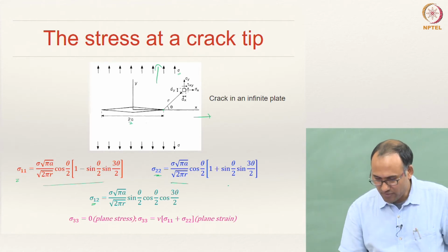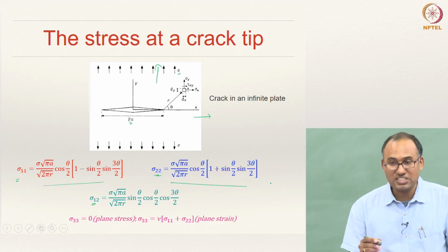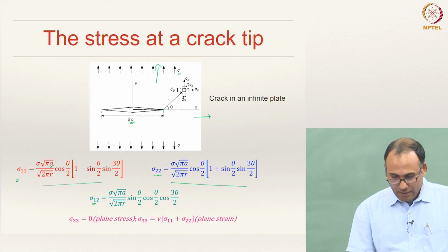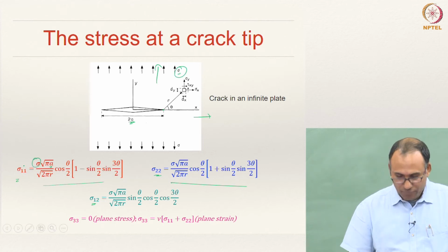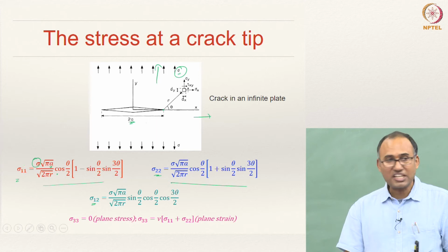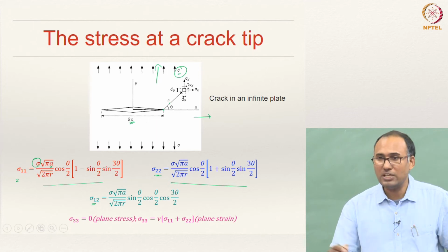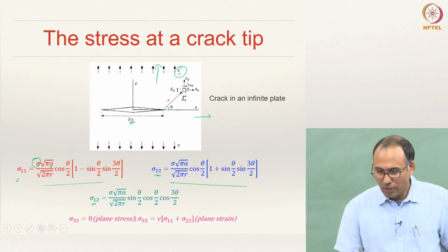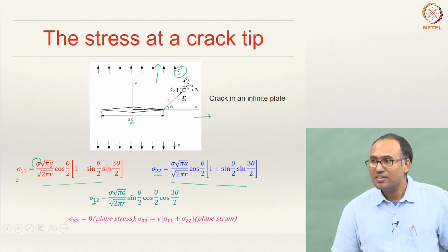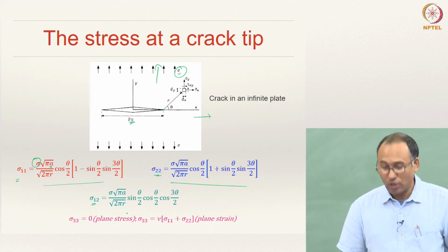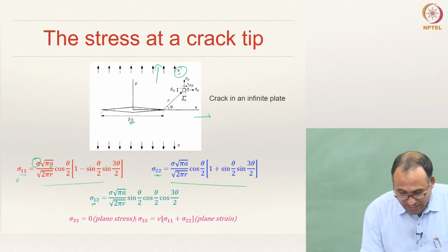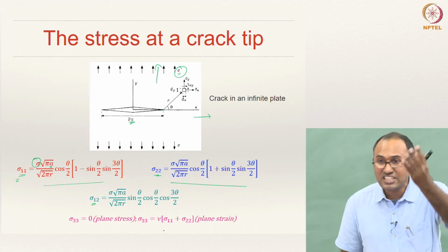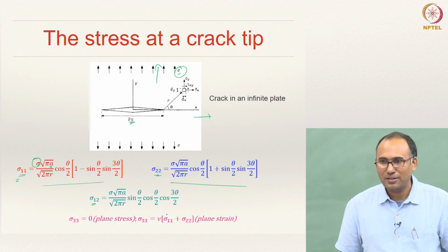This is sigma 11, sigma 22 is this, sigma 11 is this direction, sigma 12 is your shear stress, is given by this. That depends obviously on the size of the crack, a, the far field applied stress sigma, and the state of stress changes from the crack tip to far away. What happens near the crack tip, by the way? What is the value of r near the crack tip? Infinity. Sorry, r is 0, and hence as a result sigma 11 will become infinity.